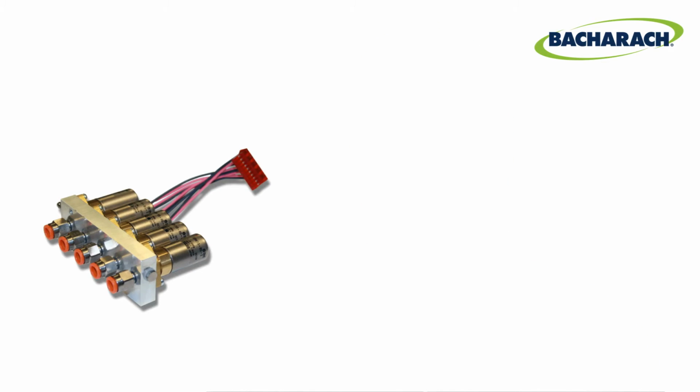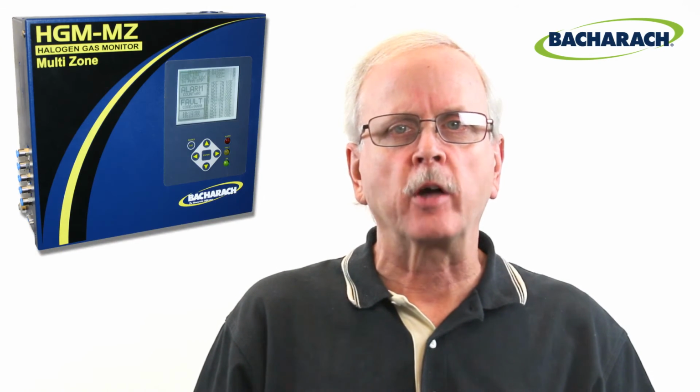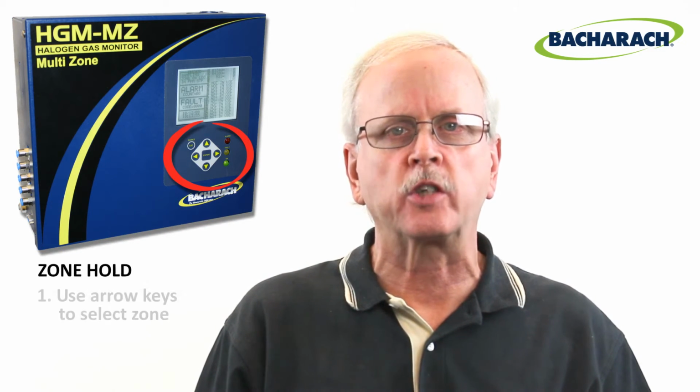At this stage of troubleshooting, a no-flow zone fault is likely to be caused by either a mechanical problem with one or more solenoids in the manifold or an electrical problem with the printed circuit board that controls the solenoids. To determine which, we'll first confirm that the suspect solenoid in the manifold is actually energizing. You see, if we can isolate a suspect zone and then somehow verify that the solenoid is indeed being energized, then we can assume that the solenoid control board is doing its job and the problem is a mechanical solenoid issue within the manifold. To do this, we must first put the suspect zone into a zone hold state.